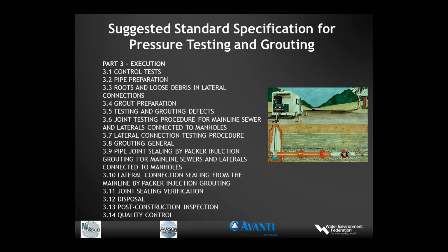Execution, all the control tests. How do you know what's going on? How do you know how much grout is going in? How the pipes should be prepared? The roots and loose debris and how they will affect the installation, and how the grouts are prepared. These are just a whole list of things that describe what an inspector on the job site would look for, how they would test the grout, and how they would verify how much grout is actually being installed, and is it sufficient.